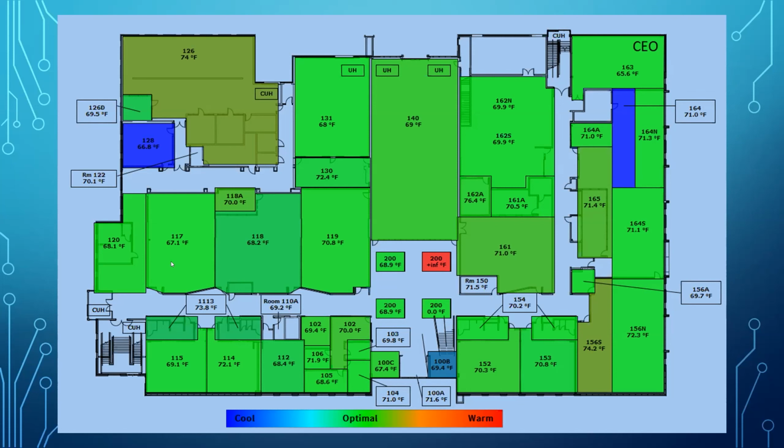So Bradley points out that our hot water temperature is probably good. Michael also says that our air handler supply air temperature is probably in an okay state. And Jenny says that it is very likely a room-based problem, so a very localized problem, which brings us back to the conclusion that we have a hot water reheat valve actuator issue or something similar to that. So thank you.